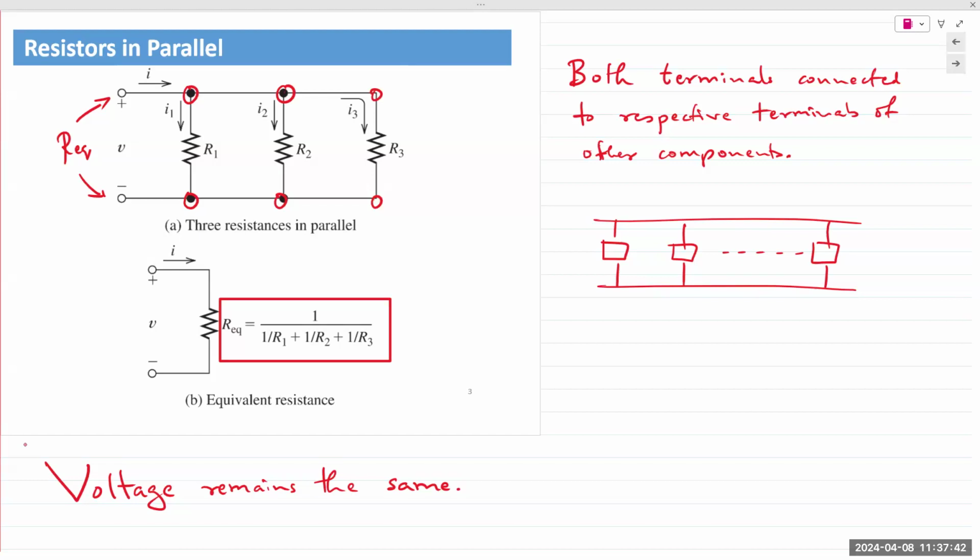You have to disconnect it from the source, then take your measurements. And again, of course, if you wish to measure individual resistance, then you have to disconnect that resistance from that large network and then measure it. Because when we measure Req, the terminals matter. Okay, the terminals of measurement will matter.